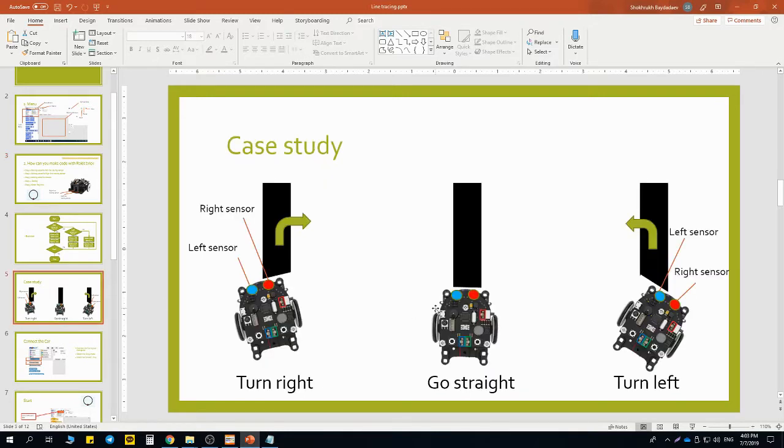Our bottom sensors detect the black line and give some values. For example, the 2 bottom IR sensors get some values when the car goes along the straight black line, but if the car goes to the right or left side, the bottom IR sensor values will change.